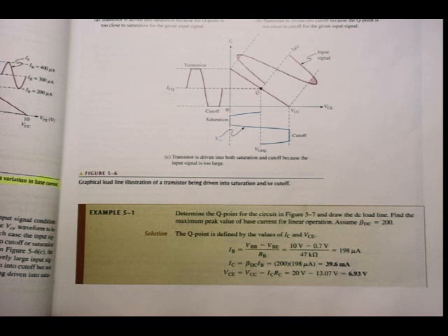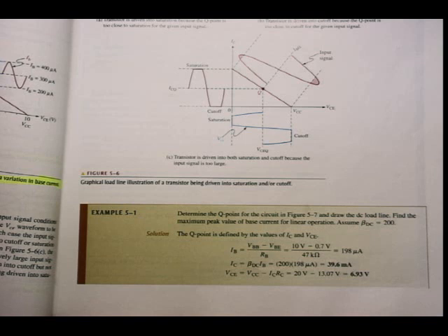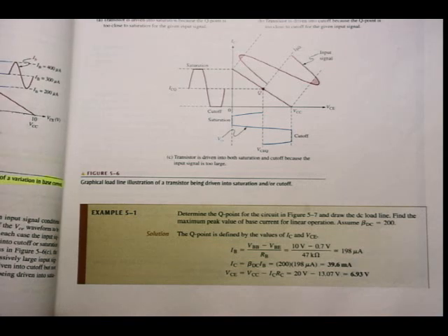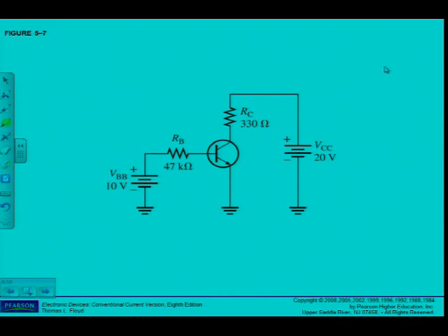Just keep in mind, you have to do your calculations accurately to 3 decimals so that we all get the same answers. Don't round off. You have to work accurately to 3 decimals and express your answers in engineering notation. Then I can calculate IC because I know the ratio beta, so IC and IB. IC is equal to beta DC times IB. I get an answer of 39.6 milliamperes. VCE, remember, if I measure VCE, what is VCE again? Just to refresh your memories again.